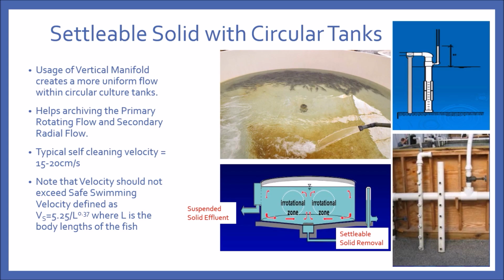However, the current introduced by the flow should not exceed the safe swimming velocity, which is defined by a formula, as it will result in excessive stress on the fish. So ideally, you would design a tank that can self-clean but, on the other hand, does not exceed the swimming velocity, and considerable effort has been placed in researching the optimum velocity.